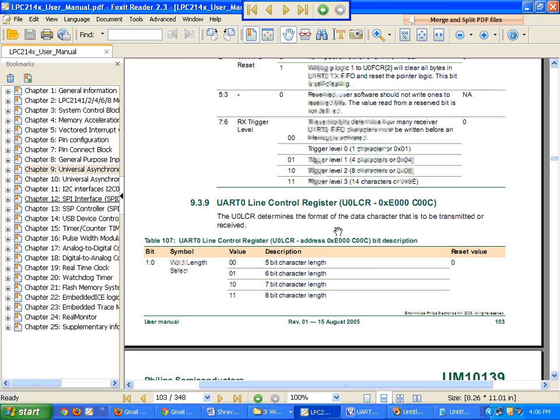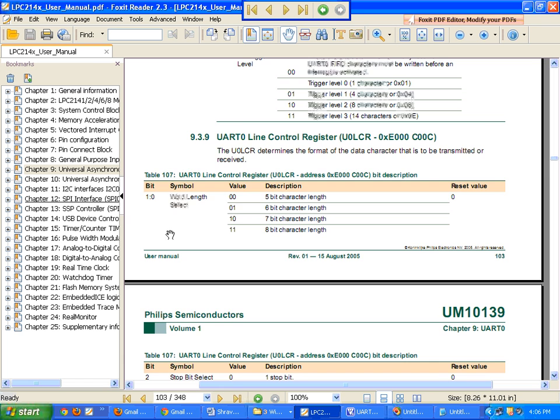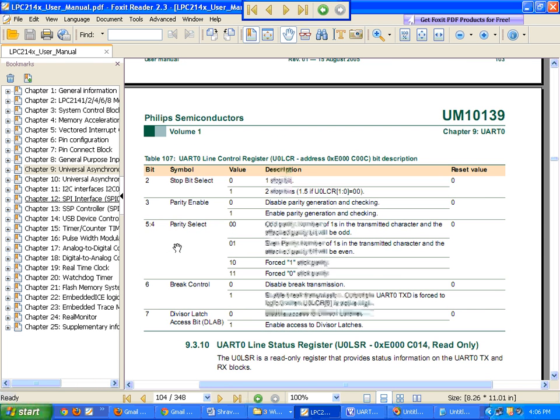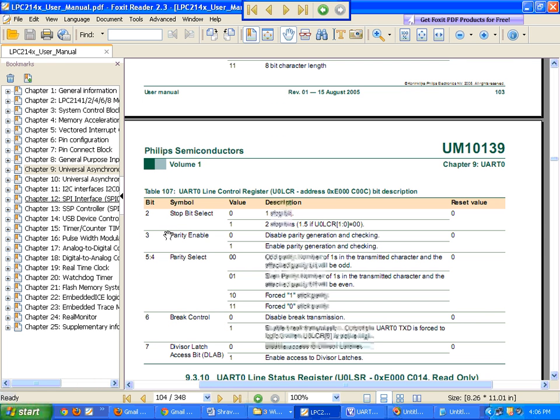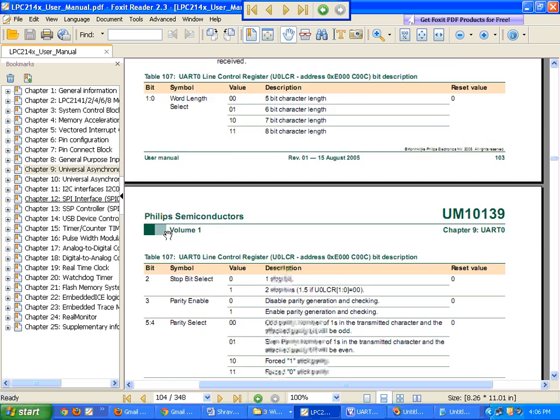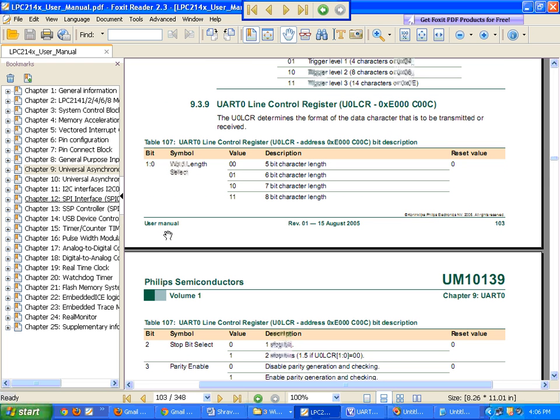See, you have to first register, you have to call LCR register. LCR register is also a 32-bit register. Okay, so total 32 bits, only 8 bits are used, the rest are zeros. You have to configure the first 8 bits. So you see, 0th and first bit is for character length. We will decide how many character length. So it will be 8-bit character length.